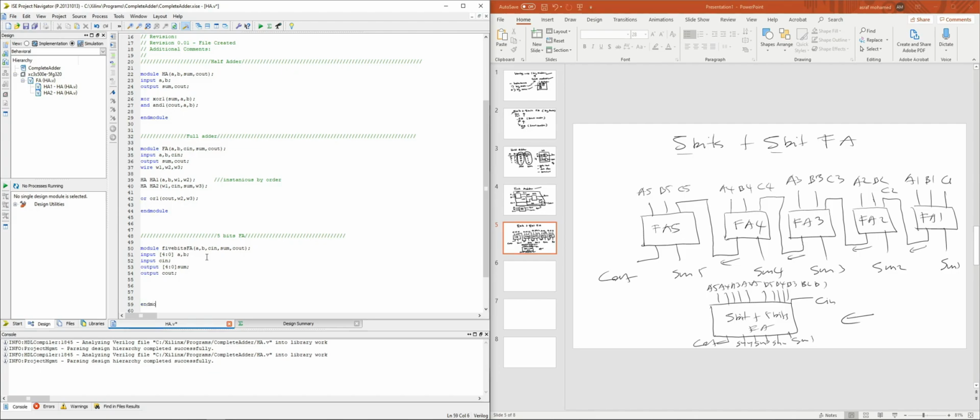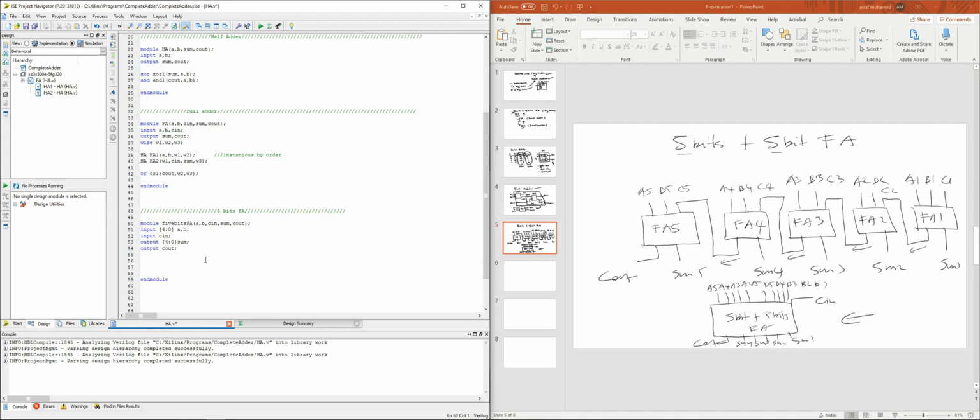You can write the end module first. Now you're going to call the full adder, right? Because here we have 5 different full adders inside this one big 5 bits adder. So as I mentioned before, copy this particular line here, Control C, bring it here, and give a unique name. Let's say we want to start from here, full adder 1. What is the input for the full adder 1? Let's say A0, because you can start from 0, 1, 2, 3, 4. We have 5 bits, right?